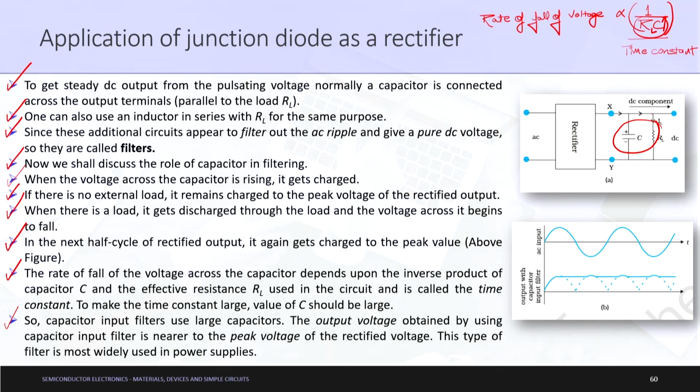We changed the circuit a little bit, we used a center tap transformer, and then we got a full wave rectifier, in which for each of the sinusoids a different diode works, and finally the output is a half sinusoid movement going on. The next difficulty was that the polarity was always the same, but it was not steady. So, to make it steady, we added filters. What is basically a filter?